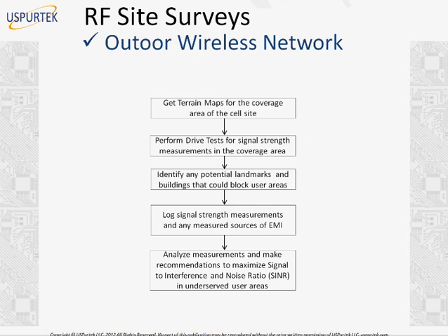Now here it's a little tricky, because once you erect a cell tower, it's very hard, costly or expensive to relocate the cell tower. So it has to be done very carefully. You have to really drive around the area and see what is the best site for installation of the cell tower. And once it is installed, for measurement of signal, again you have to do a drive test to make